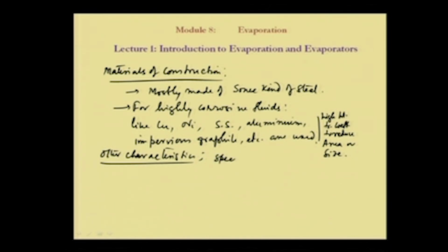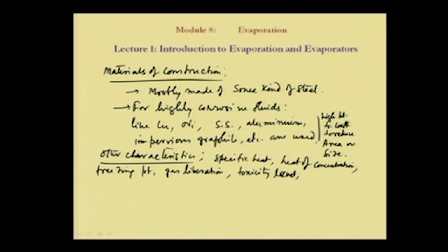There is specific heat, heat of concentration, freezing point, then of the liquid, definitely gas liberation, toxicity level, then explosion hazard, radioactivity, etc. So, these are certain information that we should have regarding the solution which we are going to concentrate, particularly for an evaporator design.